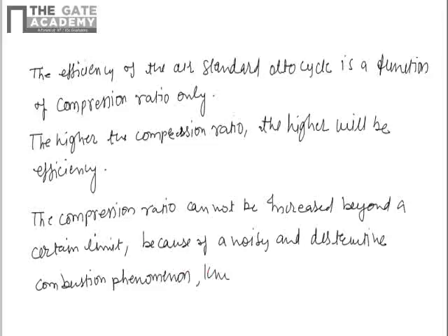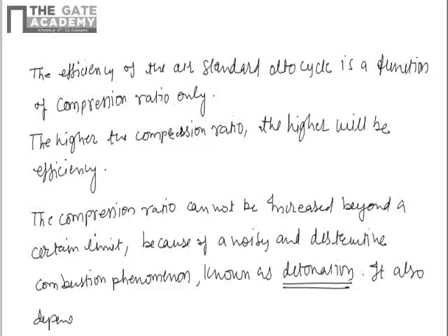That is known as detonation. If we increase the compression ratio, the chances of detonation will be increased. It also depends upon the fuel, the engine design and the operating condition.